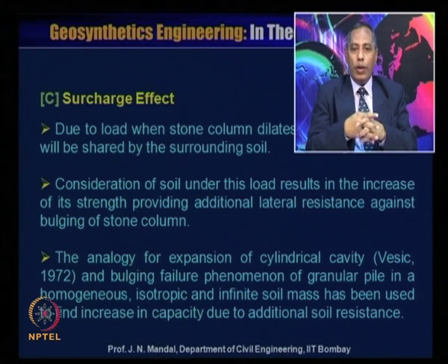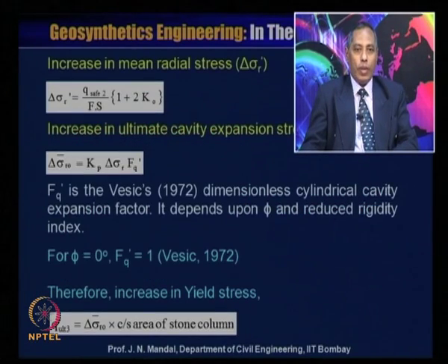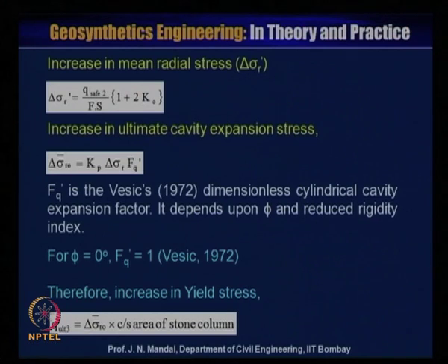The analogy for expansion of a cylindrical cavity, that is Vesic 1972, and the bulging failure phenomenon of a granular pile in a homogeneous, isotropic and infinite soil mass has been used to find the increase in capacity due to the additional soil resistance. Now, the increase in the mean radial stress, that is del sigma r dash, is equal to Q safe 2 divided by factor of safety into 1 plus 2 K0.